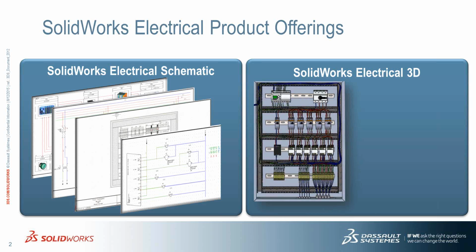Using SolidWorks Electrical 3D, you can use the schematic information that you've developed to figure out how components will be best placed in your 3D model. And from there, you can determine the best routing practices as well.